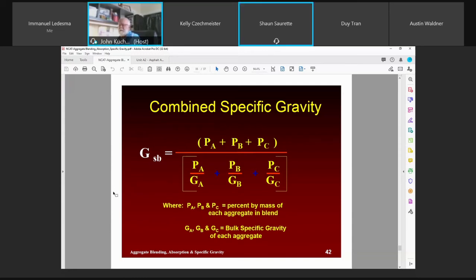No, you can just say that you used an Excel spreadsheet and you're using various trials to determine the ideal trial. The sieves were done in accordance with ASTM C-136. A sieve is a sieve is a sieve. It's got to follow the sieve analysis procedure. ASTM C-136 and C-117 are the ASTM standards for doing sieve analysis. You didn't physically do it, but it would have been done.